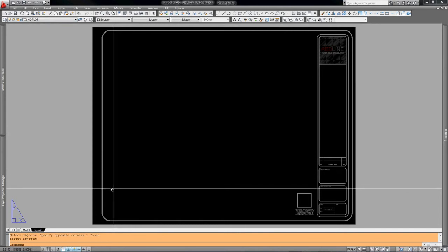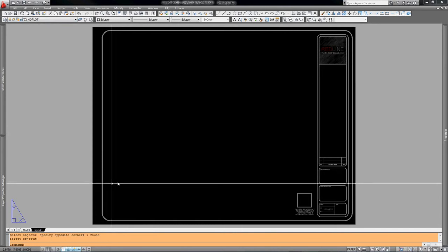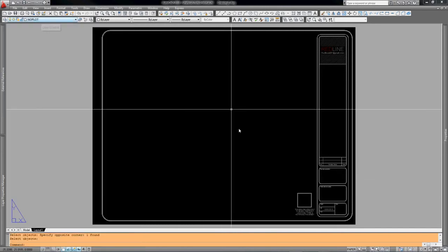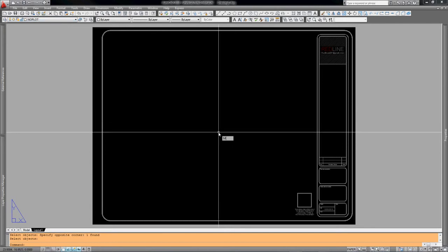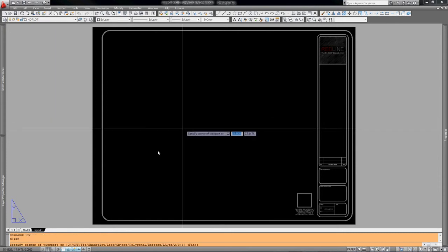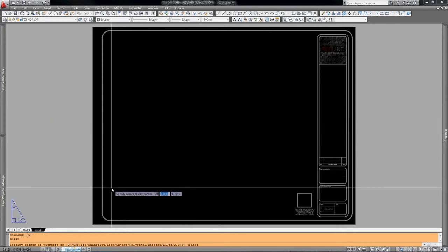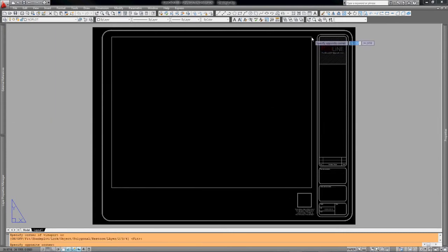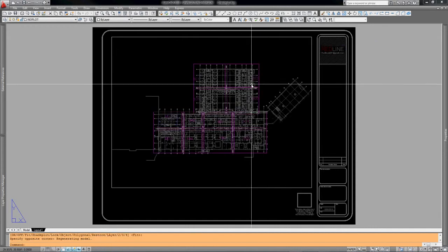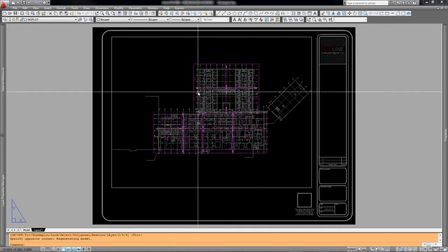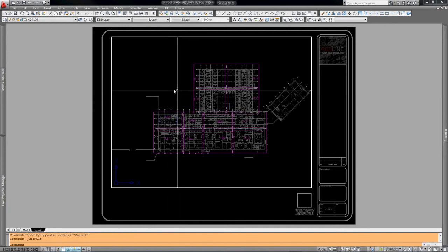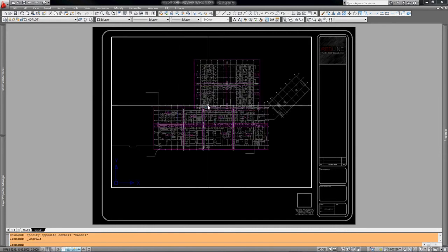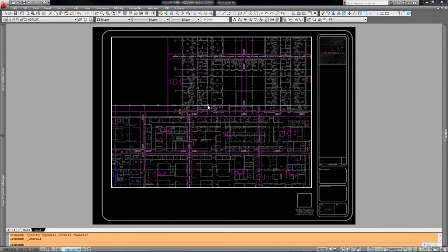You can move that thing around if you want to. I'm going to now, on the no plot layer, which will not plot in Paper Space, do an MV, as in Matthew Victor, and I will select a box in my Paper Space. And again, we're cutting a hole, as it were, right into this 36 by 48 piece of paper and allowed to look through this hole at whatever zoom factor we want to. And this is our scale factor.